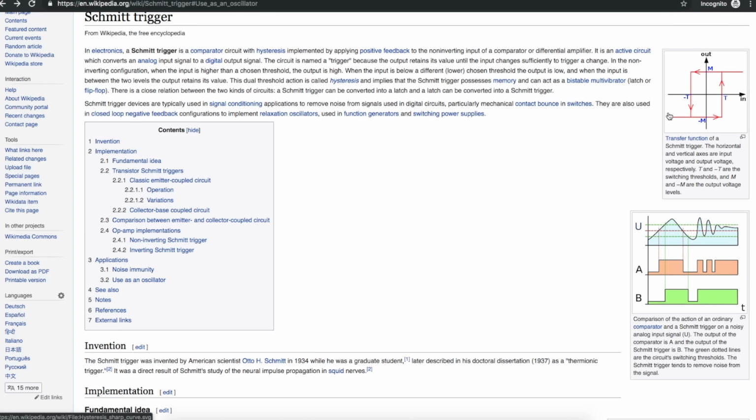What this diagram represents is if we have an input that starts at 0 volts and it's going to rise up toward 5 volts, the output voltage on this Schmitt trigger is going to be at this certain level all the time until the input reaches this upper threshold. When it does, it triggers a change of state, so now the output immediately switches to this other level. And while it's in this zone, if the voltage happens to be still rising and it's noisy and it's flipping around, say 2.7 volts, 2.8, 2.5, back to 2.7, on a regular gate, that may keep triggering high-low outputs.